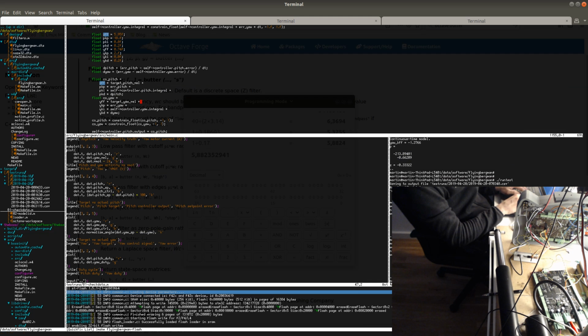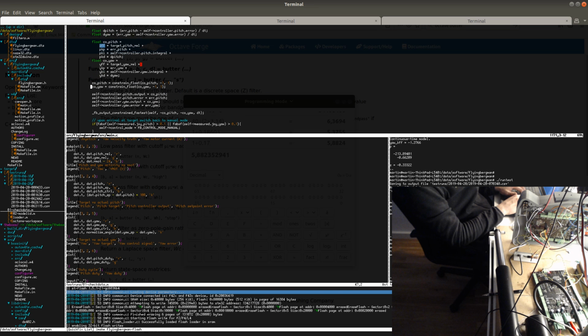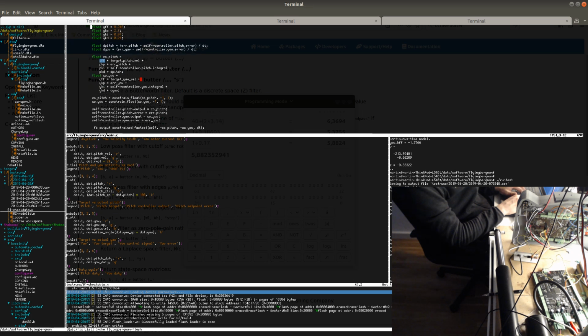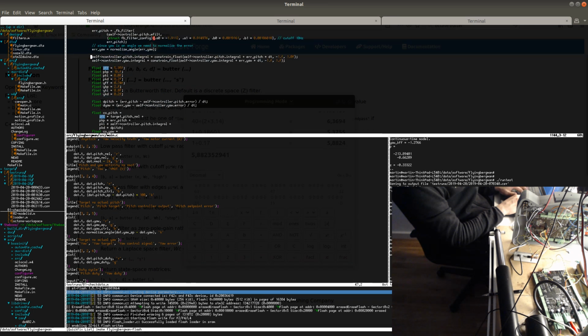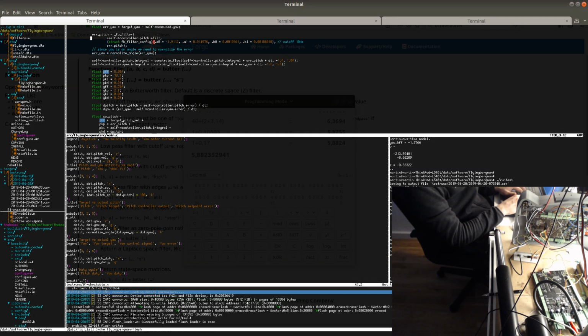So I did a similar thing for the yaw here, and next I will just move this code around, remove the hard-coded values here. The filters can be hard-coded at the moment. I'm not going to be changing these values, but the KP, KI, KD, feed-forwards, it would be better to place in the configuration, which can then be saved to the EEPROM on the board.